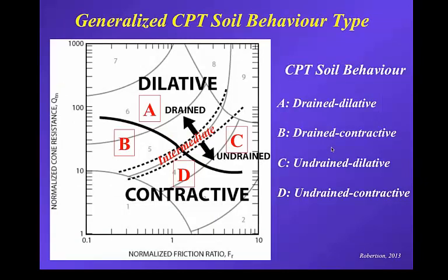Then you come across here and you can see that 10 to the minus 7 roughly is where the value of 2.6 is. So the IC of 2.6, which is normally the cutoff that I've often said separates coarse grain material from fine grain material, or drained material from undrained material, does work about right based on what you've seen there.